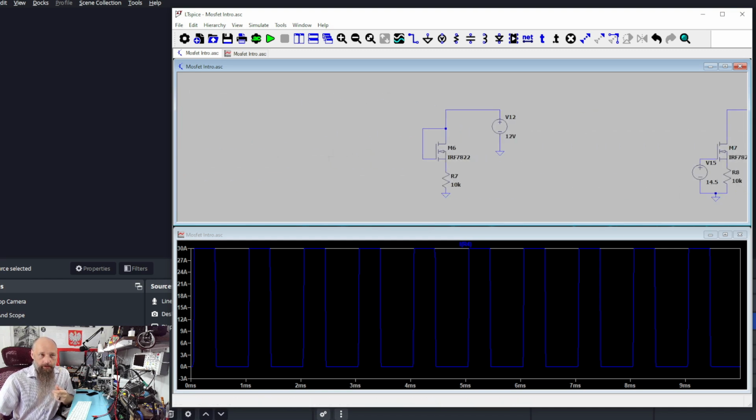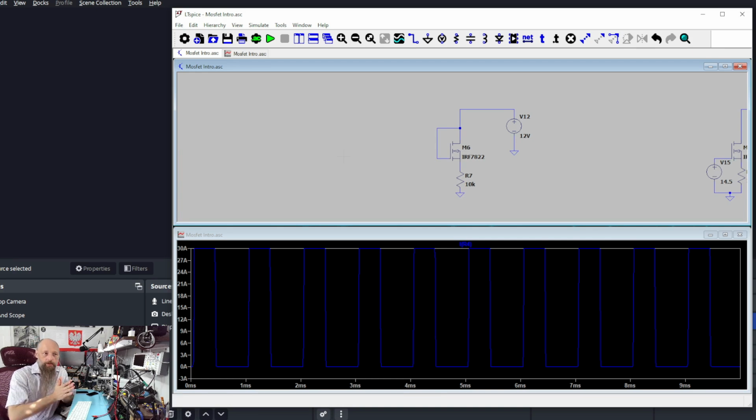However, typically in laptops, that switch delivers voltage to the rest of the circuit. It's the initial switch that is controlled by some sophisticated chip, maybe a BQ chip. It will have 2 transistors. It can detect whether one of those transistors is shorted, and if everything is good, it's going to open the first transistor, then it's going to open the second transistor.